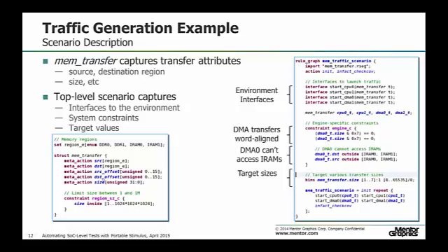There's an offset to start in different places of memory, and there's a size, which is not really that important. The size can be divided up into larger chunks to make it more manageable. We also use a constraint to limit the size of transfers to something reasonable. So this describes our generic transaction in our little SoC system.